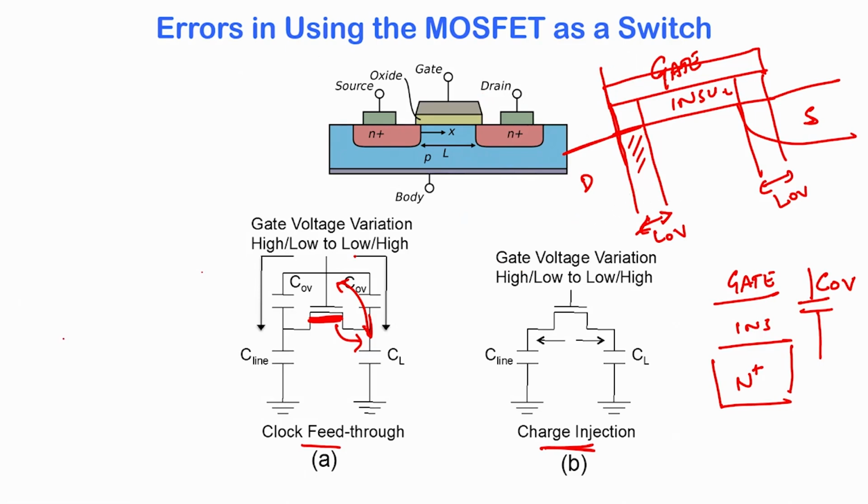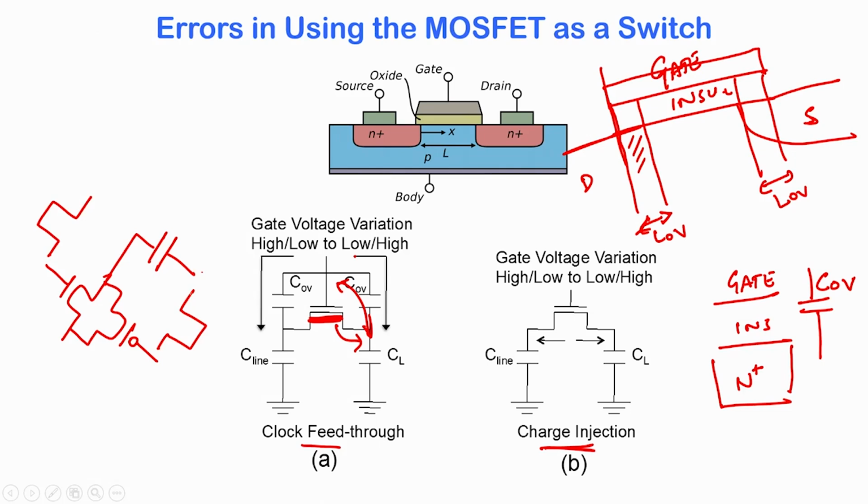In fact, for charge injection, a very useful technique is to have a complementary device. You provide this complementary device with an opposing signal. So, let us say the gate goes on and off here, the clock drives the opposing gate. Which means that when electrons come out of this, an equal number of holes also come out of the complementary device, which is basically your PMOSFET, and that is your NMOSFET, and you have electrons and holes, and therefore, you do not have any charge injection. So, there are techniques to overcome these, but nevertheless, it is a problem that you should be aware of.